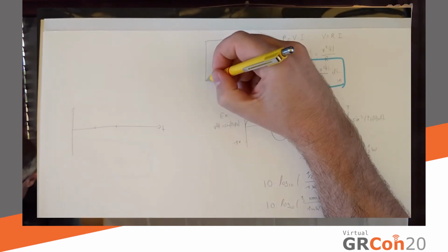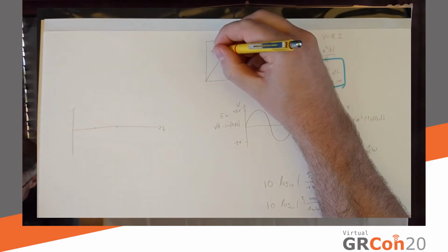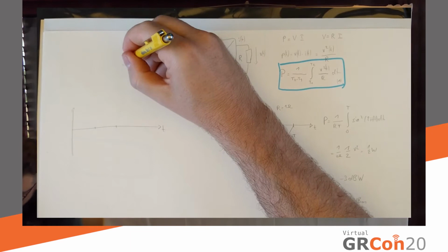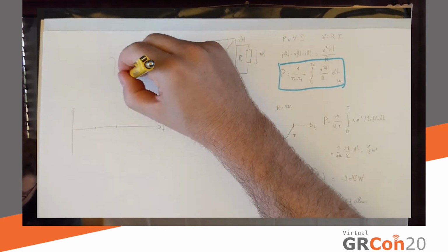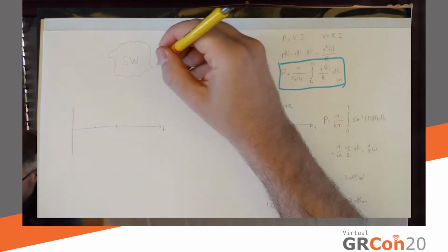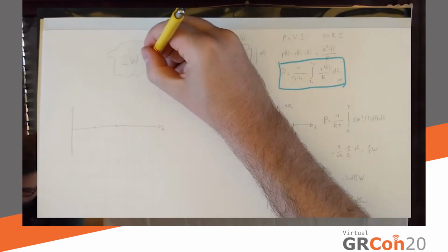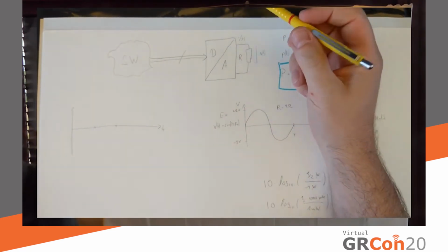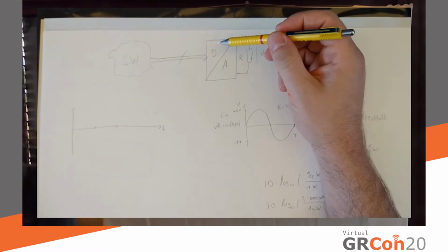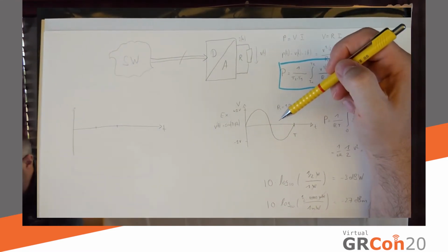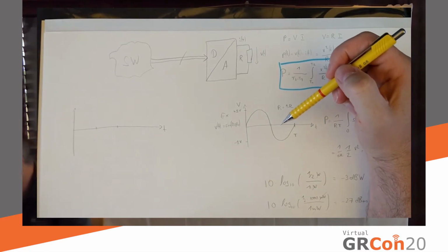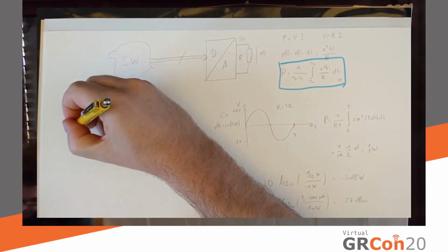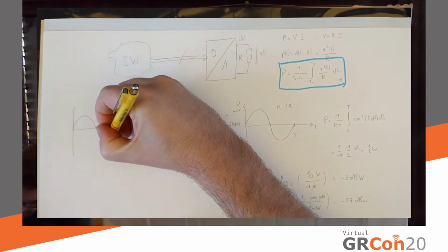Now, let's say this white box is actually a digital to analog converter. And what's feeding it is some kind of software. So this would be our SDR software, probably, or hopefully GNU Radio. It feeds into the DA converter, some bus, it doesn't matter what. In software, we can also have a sine wave. Totally, no one says we can't have a sine wave in software. In fact, we do that all the time. However, let's see what happens if I put that in my axis.